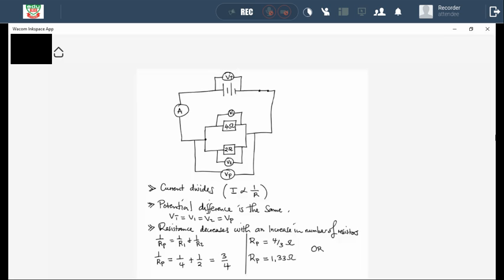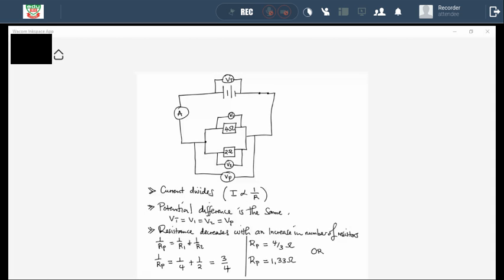So this confirms the point we made above, that whenever we add another resistor in parallel, the total resistance decreases and current increases. Now, the last point I wish to explain is that the opposite is also true. When we remove a resistor in parallel, the total resistance increases, and when the total resistance increases, the total current decreases. Please take note of those dynamics so that we won't have a problem with our calculations as we move forward.